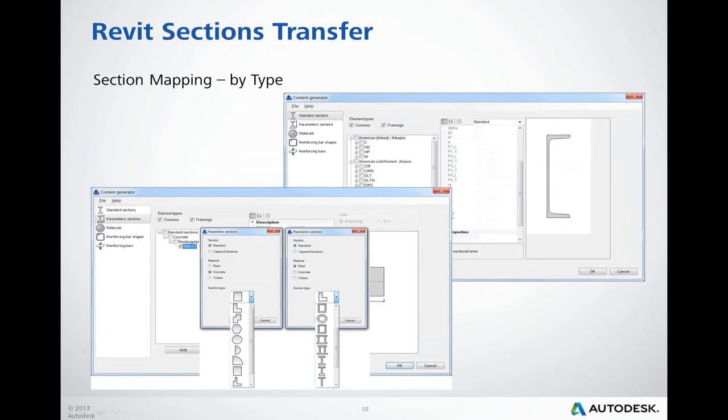Sections. Section shapes can be transferred between Robot and Revit in three ways. First, by type mapping. Standard sections such as steel database sections, Revit standard steel sections, typical concrete sections, Robot parametric steel sections are automatically mapped for correct corresponding section in the target program by the Content Generator module. Of course, this process is automatic and not visible for the user.